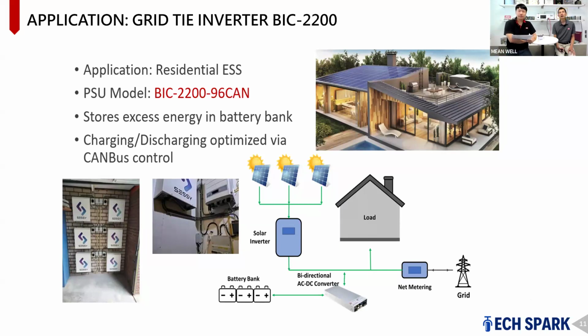Another smart thing is that this method also saves cost during peak power. Utility companies usually charge you by how much you use during peak hours, like at night, 7 p.m. to 8 or 9 p.m. During those times, if you turn on the AC and want to use the battery to run it, it saves you cost. So this achieves what we call peak shaving, for energy saving.